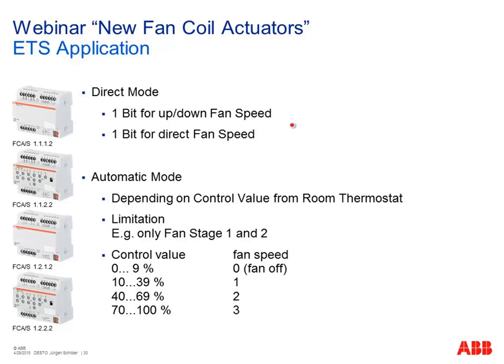Both are possible. And if you have automatic mode, means the room temperature controller is responsible to run everything. The control value will be sent out, and depending on your value, as already mentioned, you have different fan speeds and different positions of the valve.